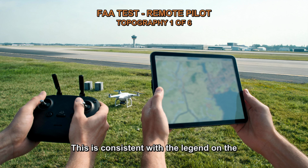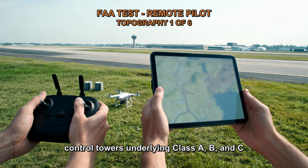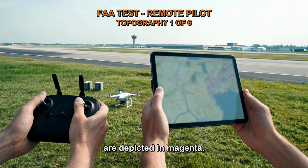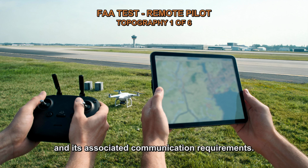This is consistent with the legend on the Sectional Aeronautical Chart, which shows that airports with control towers underlying Class A, B, and C airspace are depicted in blue, while airports with control towers underlying Class D and E airspace are depicted in magenta. The use of different colors helps pilots quickly identify the type of airspace underlying the airport and its associated communication requirements.